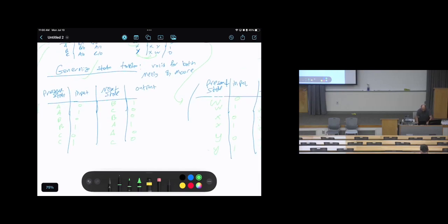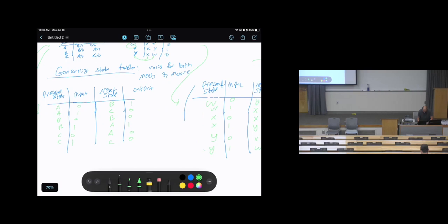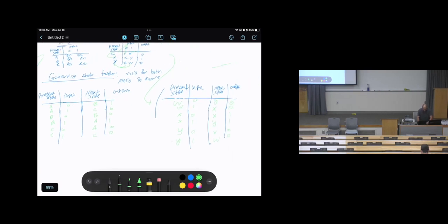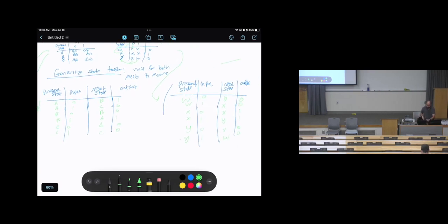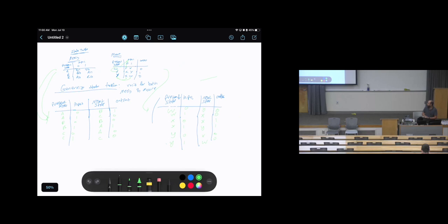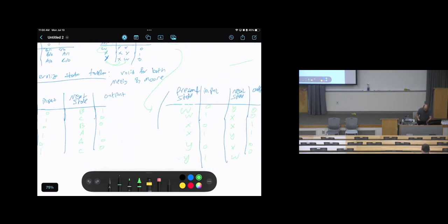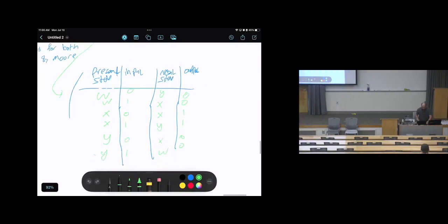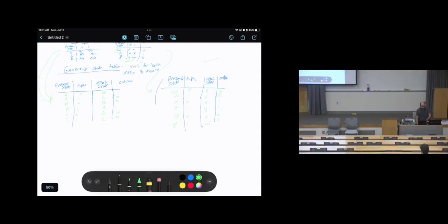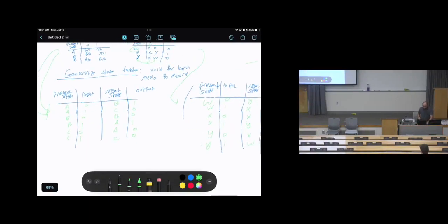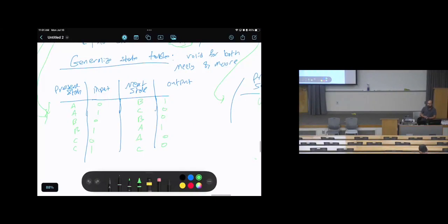So overall, you can compare between these two tables. We already converted Moore's model into a small table like this, and the Mealy model into a small table like this. The advantage of this generalized table is that it can handle these two with one table. We can make the generalized table, then we don't need to worry about the notation.